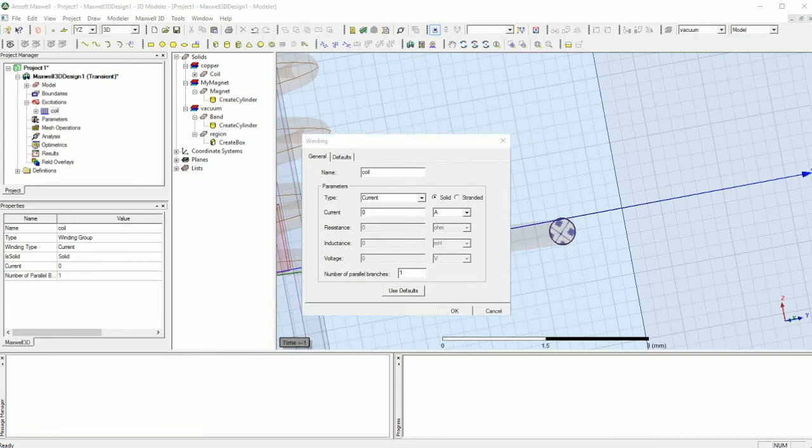So we need to be able to tell the simulator that this is going to be only to see how much current is going to be excited inside due to the fact that the magnetic pole is moving inside. To do that, you have to say this is not going to be me exciting it, it's going to be excited outside through the movement. So the trick here is to use external.